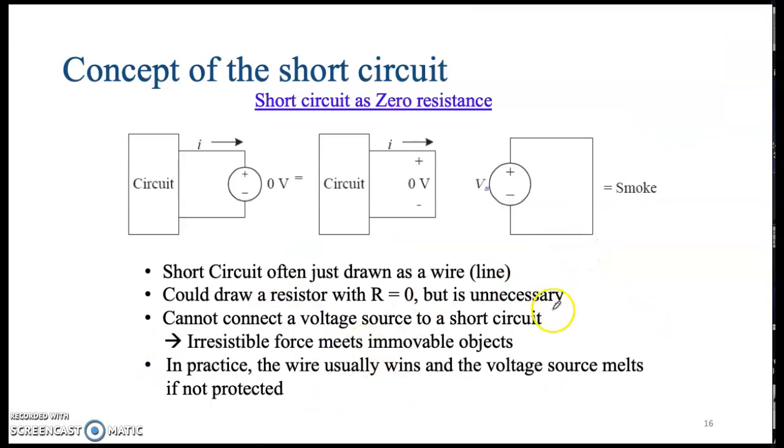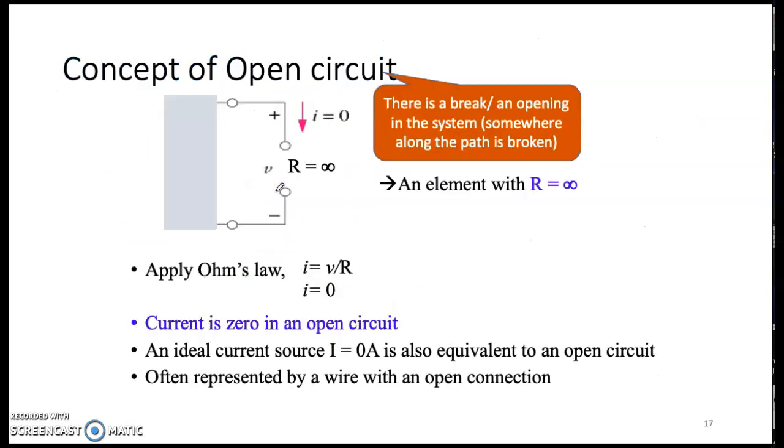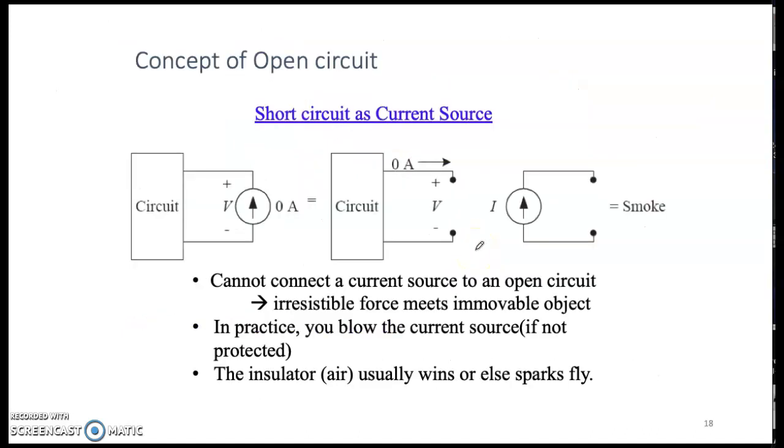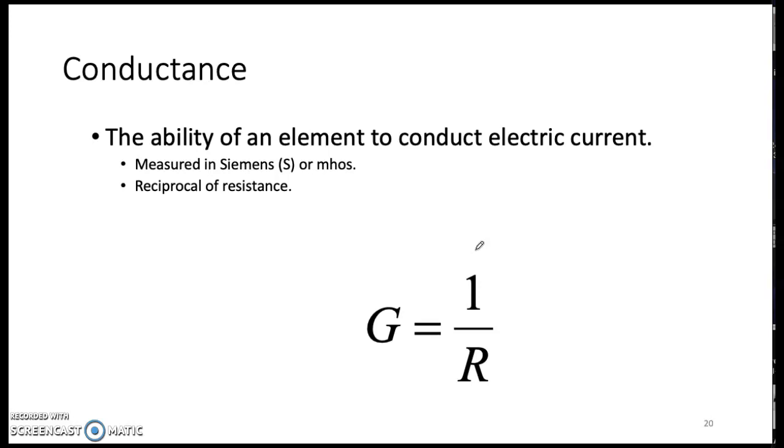Okay, so this is more explanation here. If you have a short circuit, there is no voltage drop here. It is 0 volt and current can easily pass through. This happens when R equals 0. But when R is very high, it goes to infinite, so the path seems broken because it is blocked, right? Remember, our resistance limits the current. So now here becomes an open circuit. So this is the concept.